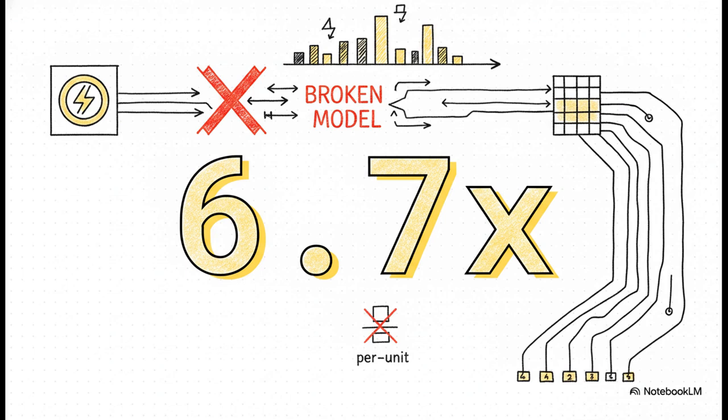They are absolutely massive. If you take a 15 MVA generator's 15% nameplate reactance and plug that straight into a 100 MVA system study without converting it, you don't just get a tiny rounding error. Actually, scratch that. It's more like a mathematical grenade. You literally create a devastating 6.7 times error. Boom! Your model is instantly broken and you've completely thrown off every single fault and load flow calculation downstream.